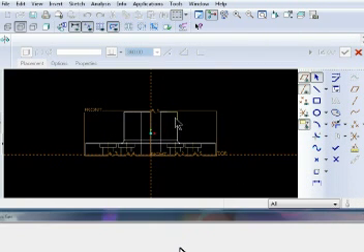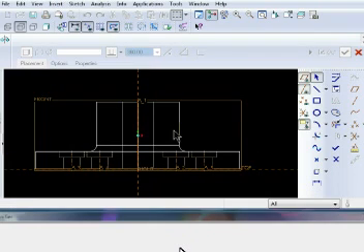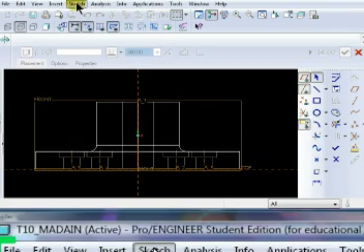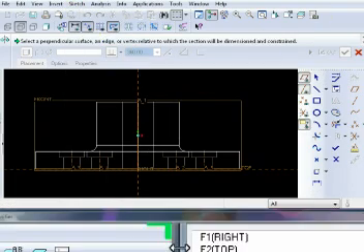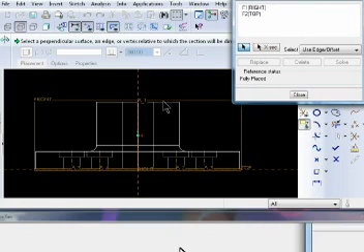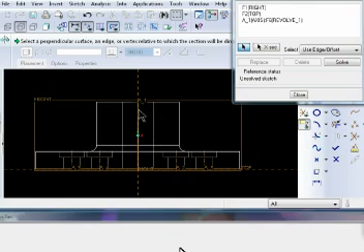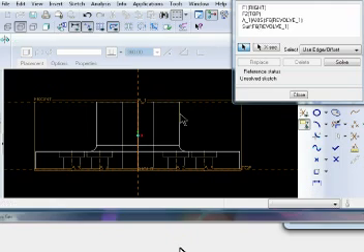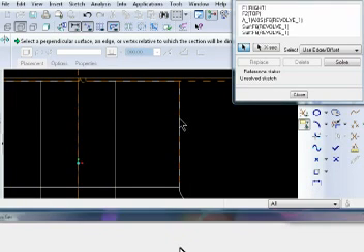Now the cut is going to be a rectangular shape right here, and it's going to be revolved 360 degrees around the part. We need to reference these lines here. We need to reference the center line. We need to reference the top surface and the side surface. So click on Sketch, References, and as the reference dialog box opens, select the axis here, and you can see an axis up here, top surface and the side surface. And click Close.